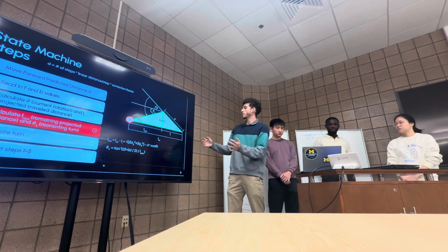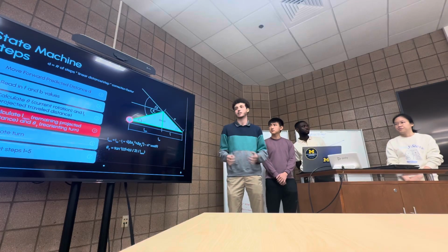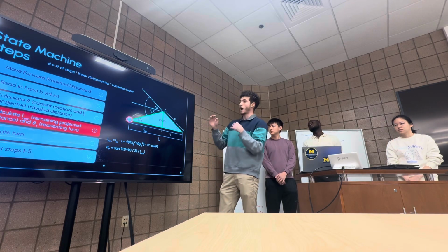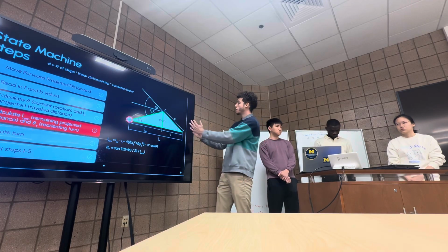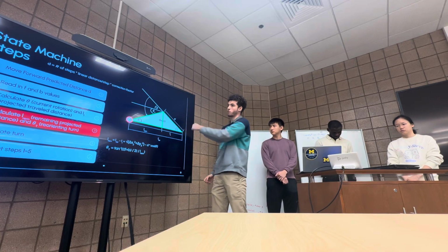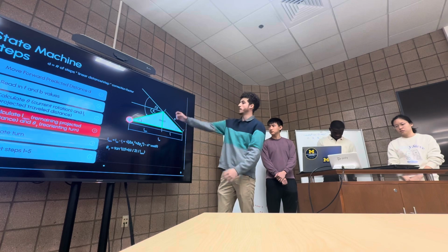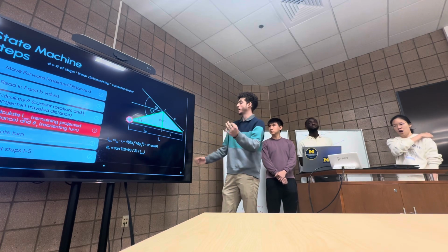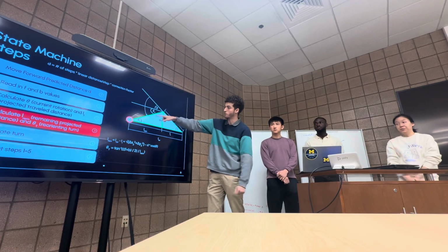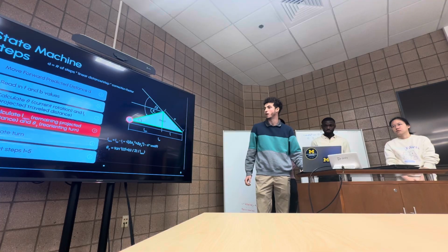And then we can subtract the current distance that we've traveled, this L1, from the L total, which is our previously calculated X distance. This gives us a remainder distance that we still have to travel. Now we have to figure out how exactly we want to turn to arrive there. We already know that in order to make our path parallel to the line we want to travel, we have to reverse the turn that we've currently made, or reverse the path that we've currently taken to get off course. And then we need an additional term, theta t, but we can calculate theta t because this line is parallel to this line, and so we have this cross section, this angle is equal to this angle. Do some nice trig, and that should give us an approximation of where we're going to travel.